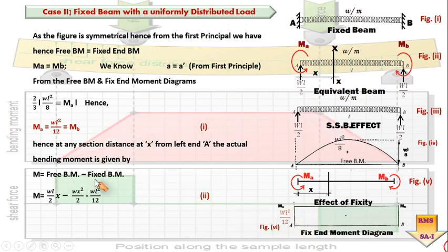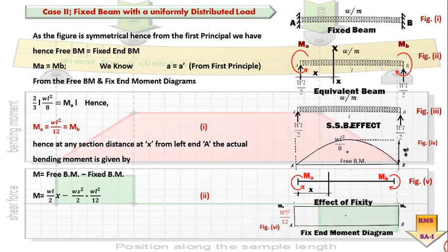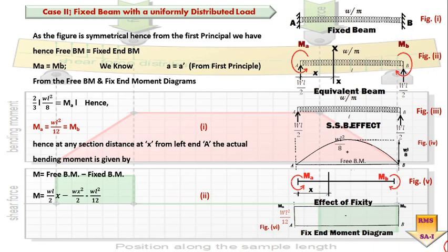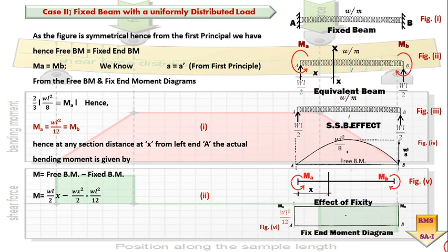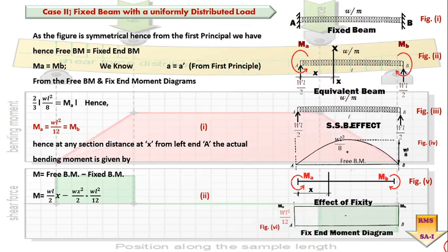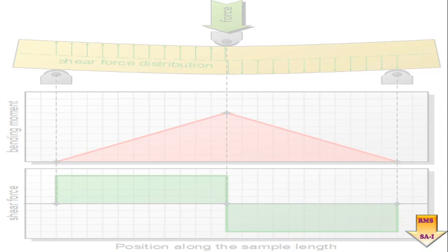For that particular reason I have to work out certain things. I know what the basic mathematical equation is that we are going to use for finding out the slopes and deflection, that is EI d2y by dx square is equal to bending moment, and here the bending moment is the resultant bending moment at that particular center, which will be found out in the next slide.